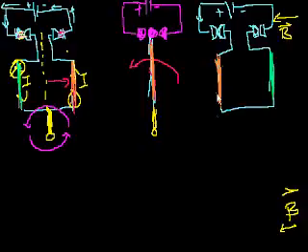So what happens here? Now this side, all of a sudden, instead of being connected to this lead, is now connected to this lead. And this green side is now connected to this lead. So something interesting happens. Now the current on the left side is still flowing down, right? And the current on the right side is still flowing up. So we're back to this configuration, except that this contraption has flipped over. The brown side is now on the left, and the green side is now on the right. And what that allows is that those net torques are still going in that same rotational direction.